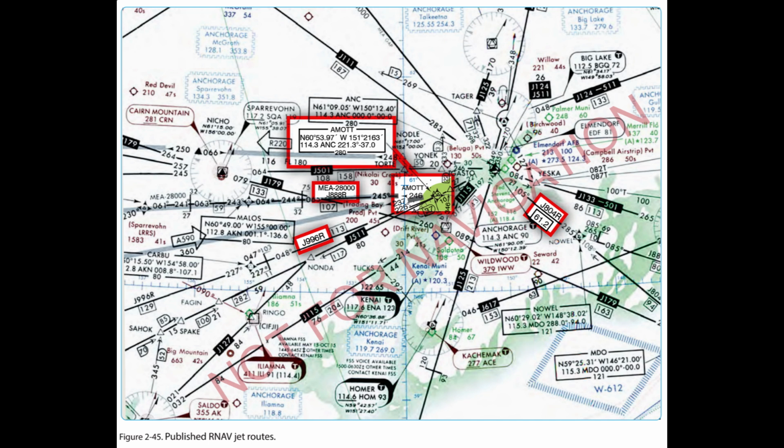Although coordinates were originally included for aircraft equipped with an inertial navigation system (INS), they are now a good way to cross-check between the coordinates on the chart and in the Flight Management System (FMS) or Global Positioning System (GPS) databases to ensure you are tracking on your intended en route course.